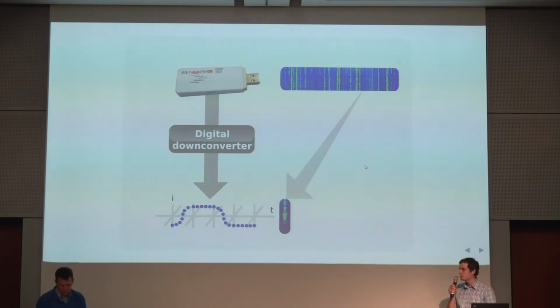And so how do we start demodulating BPSK31? If you have an SDR hardware, then that gives you, for example, 2.4 megasamples of baseband IQ data. An RTL SDR does that. And we need to select a single channel that contains only our BPSK31 signal, so we use a digital down converter that's already implemented in CSDR, so I didn't have to work much on that.